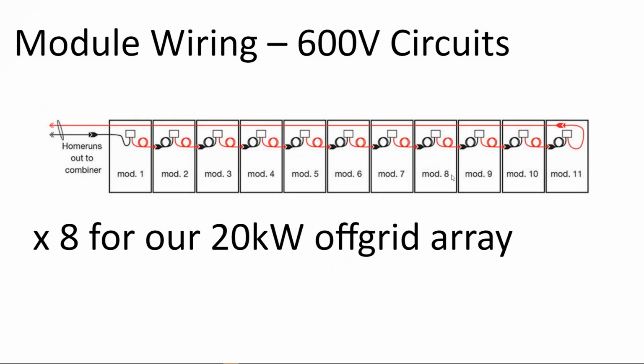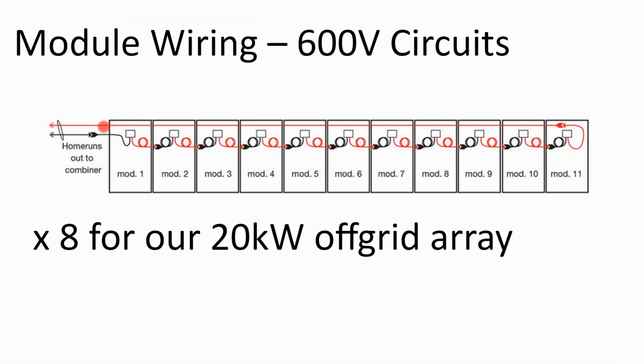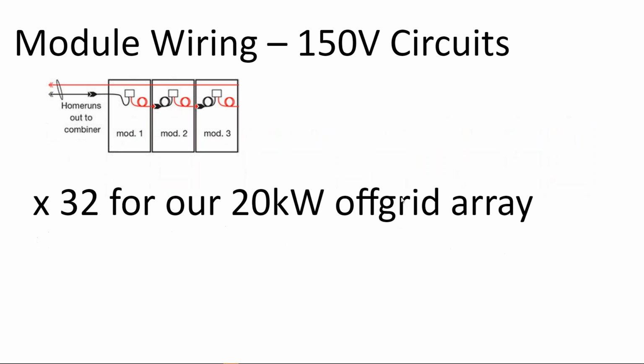So, one advantage of 72 cell modules under the right kind of racking situation is you can use skip stepping or leapfrogging and have your circuits start and stop at the end of the same place. And that's where a really good solar designer is incorporating all of that into the array layout to make the module circuits lay out in the most straightforward and logical manner possible to assist the installation and maintenance, so that you don't have to go hunting where all of these circuits are starting and stopping up on the rooftop.